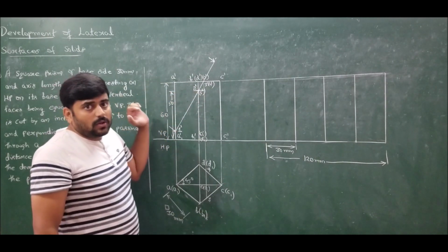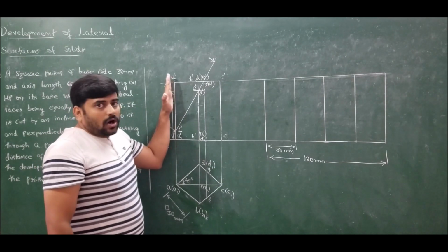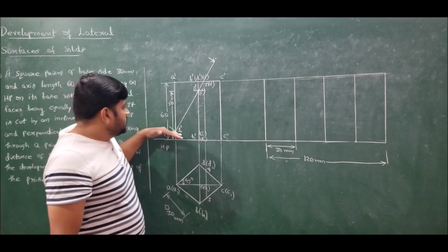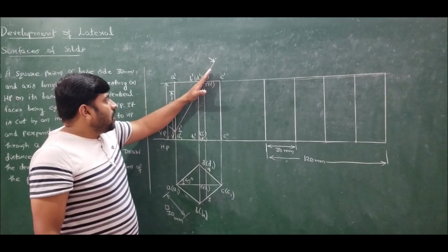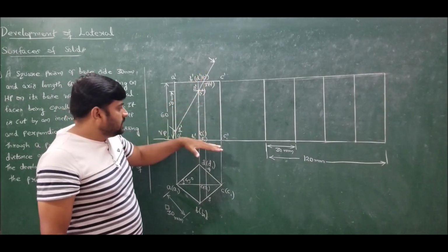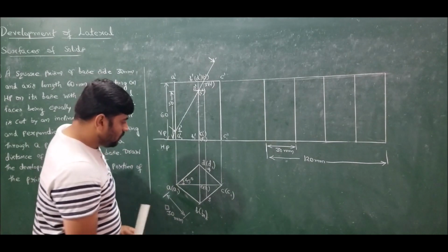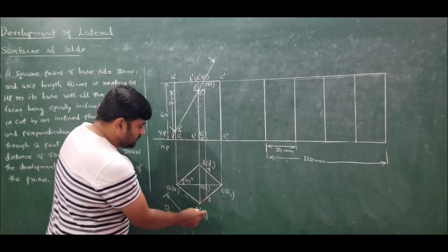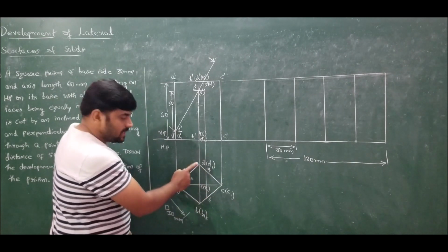And find out their locations. If the locations are sighted on the longer edges, no need to worry. Just we can take the parallel line and plot it. If it is sighting on the shorter edges, whether it is at the base or at the apex, it should be measured from the top. So therefore, how much is the length of 0.3 from B and also how much is the length of 0.4 from D is required.